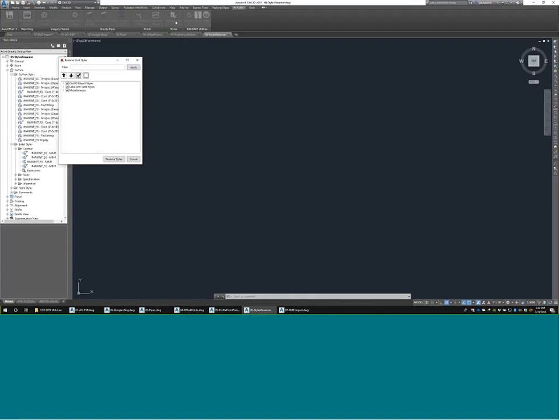In Style Renamer, we give the option to filter, and the first part of the dialog box is, all right, what do you want to rename? If we're talking about object styles, we list them all. Are we talking about label styles, table styles? Just what do we want to rename? By default, we are looking at everything, but we do have tools to deselect everything, select everything, expand, et cetera.